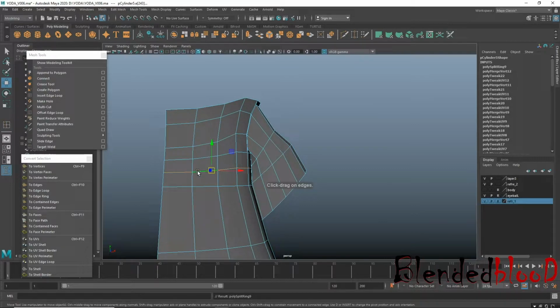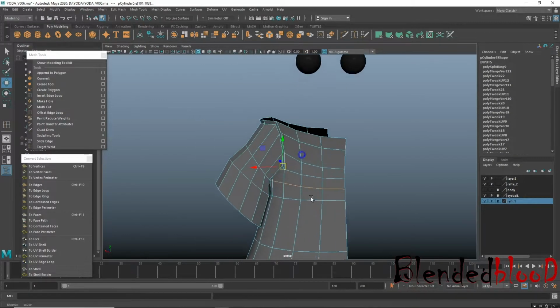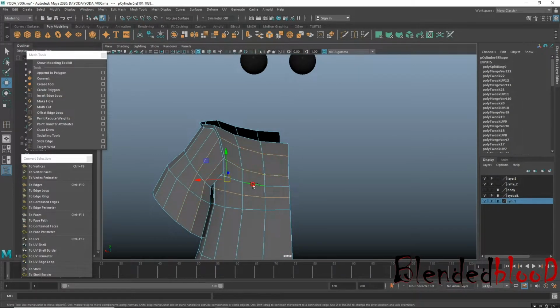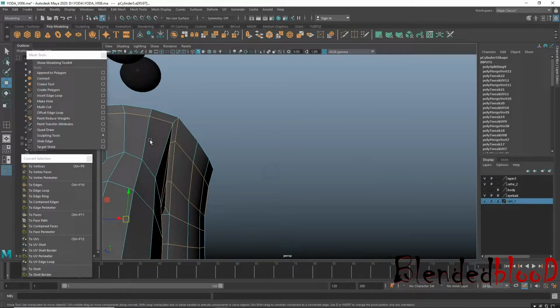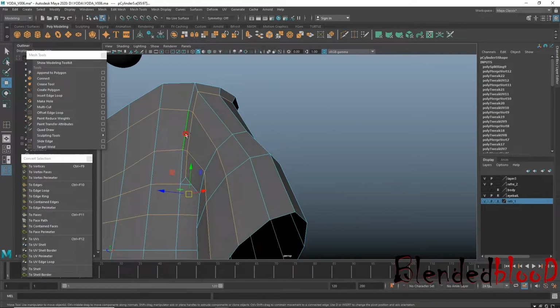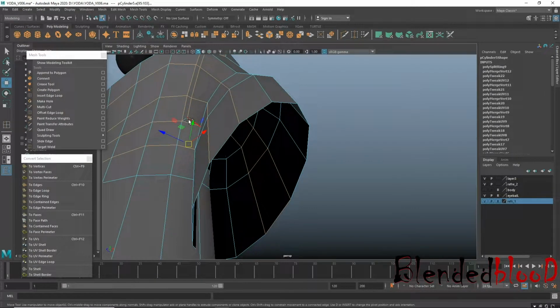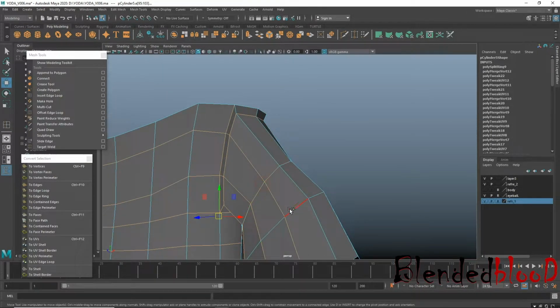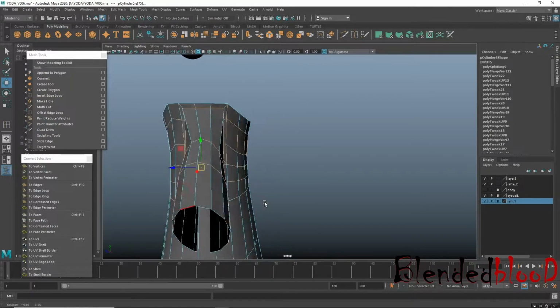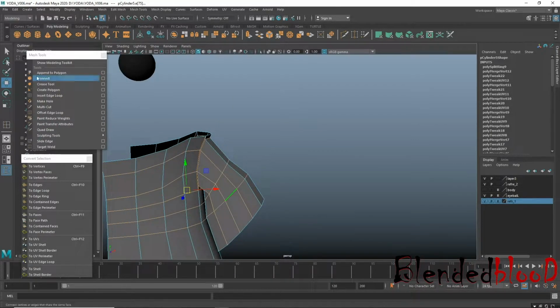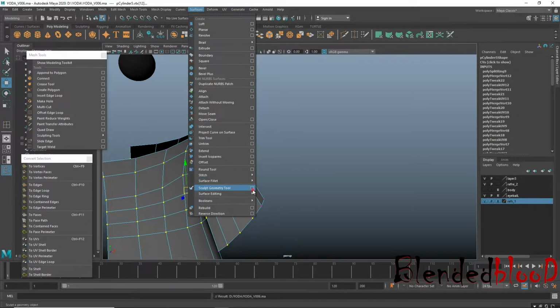Okay, double click, double click, double click. What I am doing, I am selecting these edges because now I have to use the surface sculpt tool. Mistakenly I just said scattering. Okay, after selection, convert it to vertex, Control S, surface, sculpt geometry,